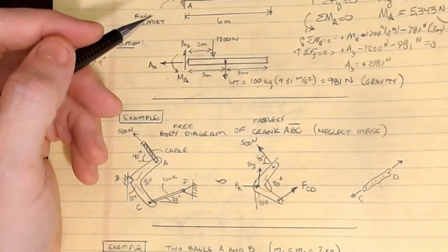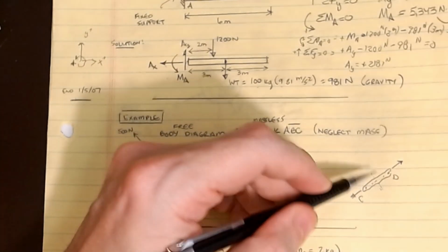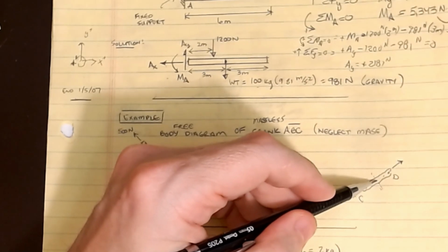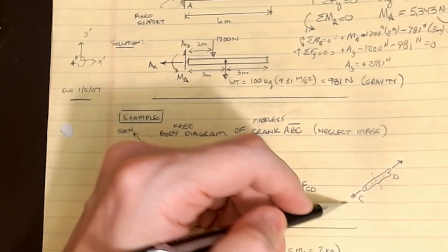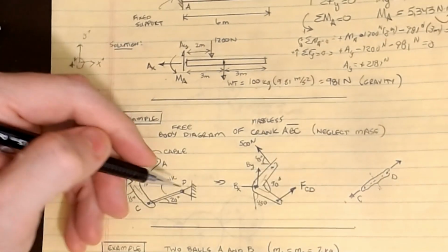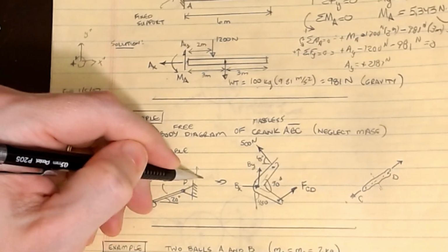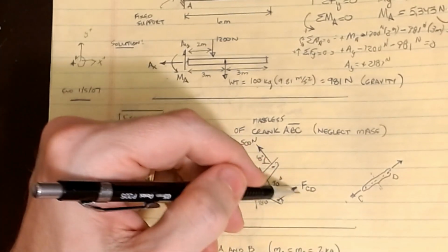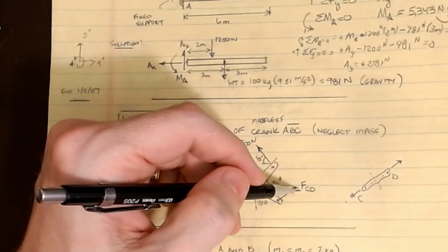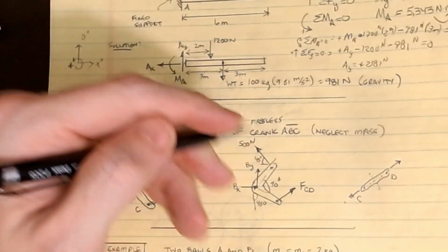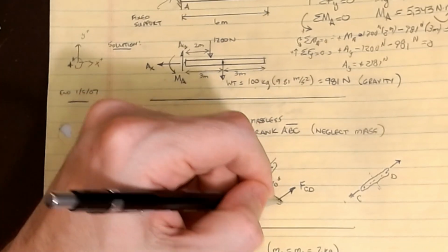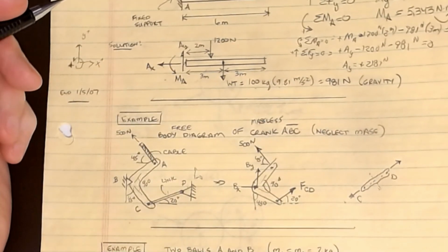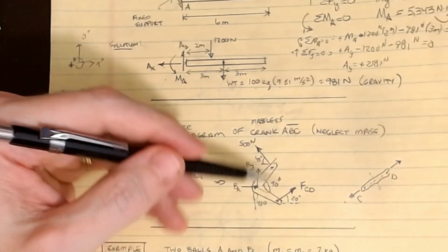And so this guy, if I choose to cut it, is that tension example we talked about last time: there's an internal force inside of this that's equal to the value of the pull. So what I've done is taken what was a Dy and a Dx, cut the rope, and replaced the force in the rope, instead of the two forces at D, with a single axial force, FCD. And if I do that, then this force is clearly going to be at 20 degrees also. That would be the type of picture you would have for this object.